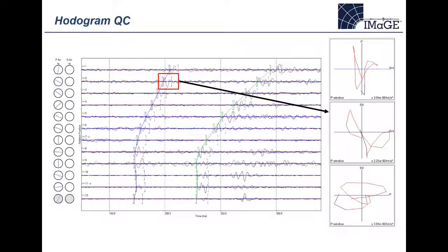Occasionally for projects, there will be one or two perf shots or ball seats that are very noisy, and so you just want to discard them from any calibration or orientation exercises because they might throw off the overall result. If you only have a couple of control shots to use, then you might be forced to use them and not have much of a choice, but ideally you'll have 4 or 5 shots or more, and eliminating one of them because it was noisy won't be too bad.